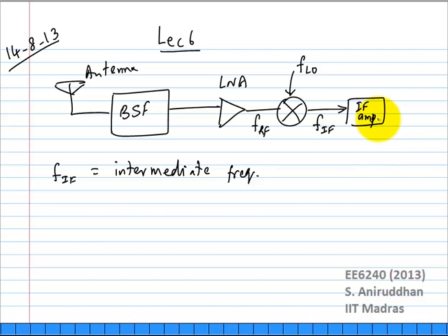Let us say I had an amplifier, okay, gain was exactly 1. Let's say my LNA I am choosing such that gain is 1 and phase is minus 180 degrees. What will happen? Will it start oscillating? Why not? You need to have feedback, right? All the phase margin criterion tells you is, if you take the system and apply feedback across it, then it tells you something about the stability of the system.